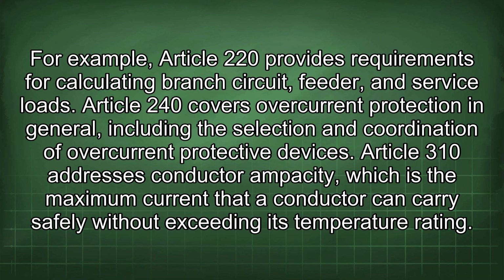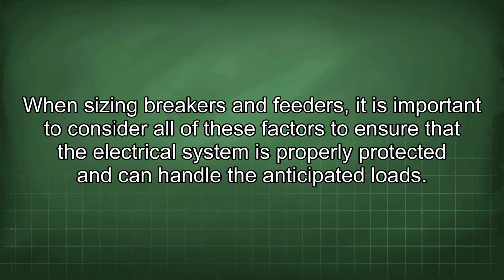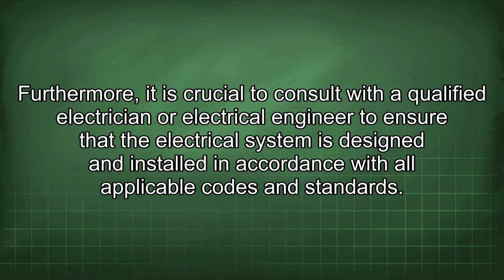Article 310 addresses conductor ampacity, which is the maximum current that a conductor can carry safely without exceeding its temperature rating. When sizing breakers and feeders, it is important to consider all of these factors to ensure that the electrical system is properly protected and can handle the anticipated loads. Furthermore, it is crucial to consult with a qualified electrician or electrical engineer to ensure that the electrical system is designed and installed in accordance with all applicable codes and standards.